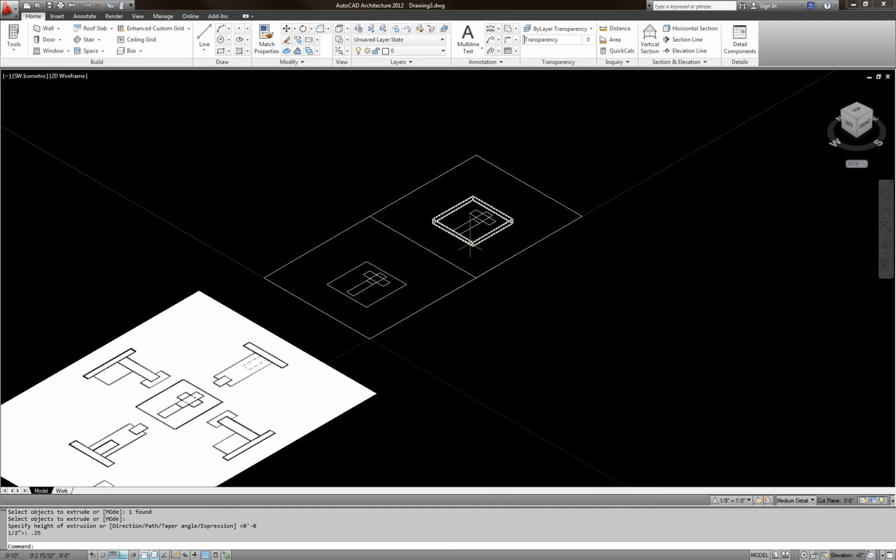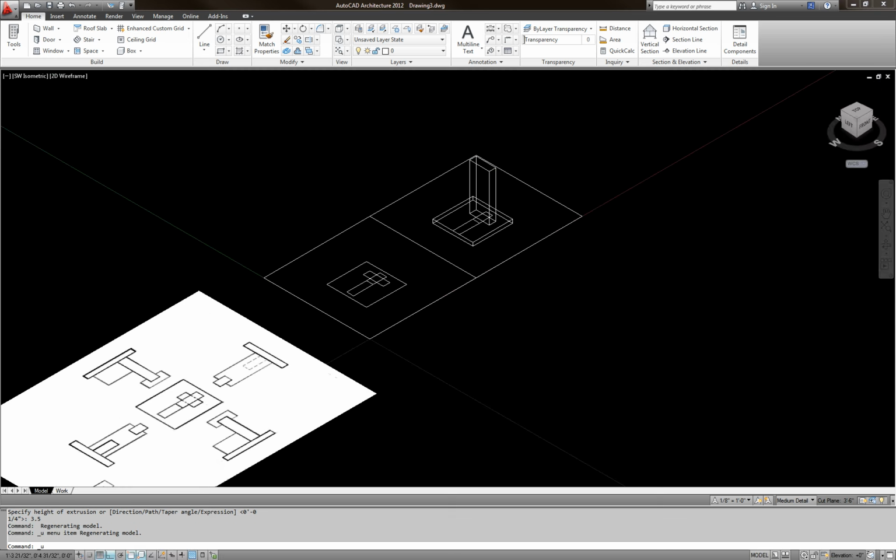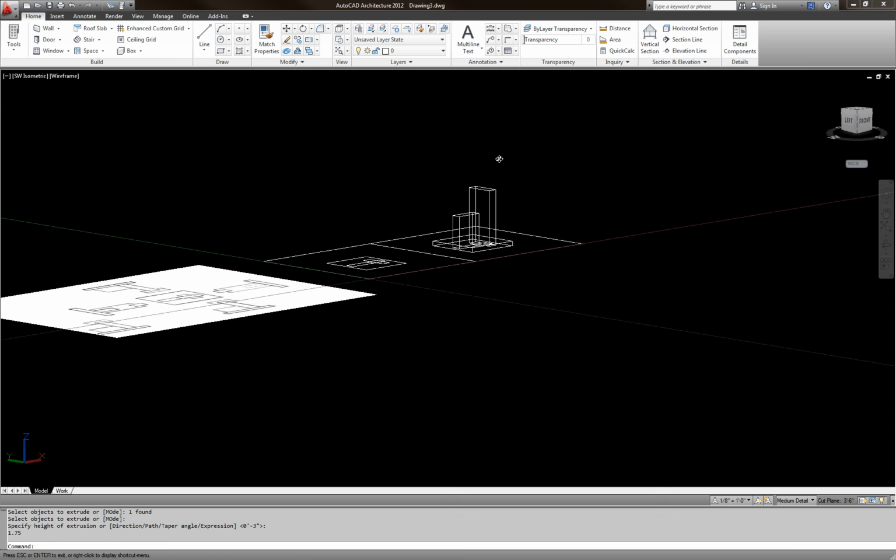Okay. Now I'm going to extrude this from here to here. Remember that this is 0.25. Okay, the base. So now I'm going to extrude this guy here almost 3.5. So ext, this guy, extrude that 3.5. Okay, I think it's not 3.5, it's 3. ext, extrude 3. Okay, now I'm going to extrude this guy here 1.75. You guys see that?